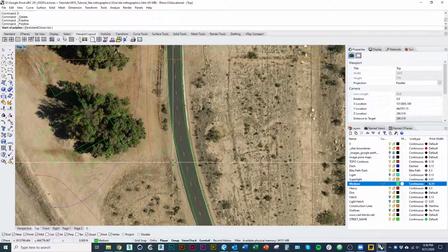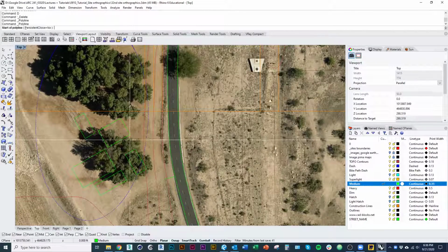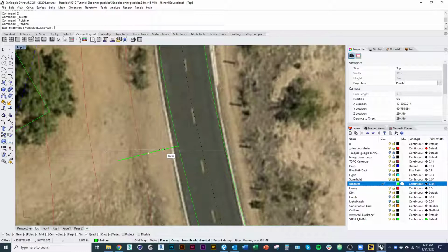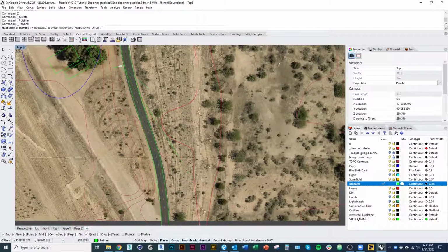The other thing I want to mention here quickly is you can see we have those contour lines showing the drop off from the height of the bicycle path down towards the pavilion. And what I want to do for that is start about midway between where the bike path is and that first contour, because even though it's close, the next contour up is a little further back.